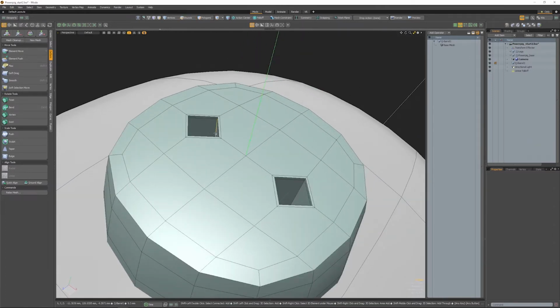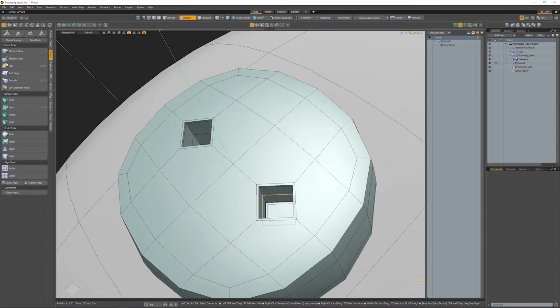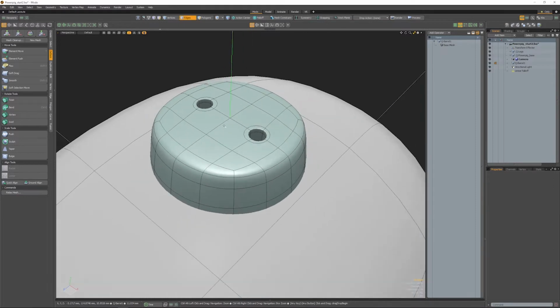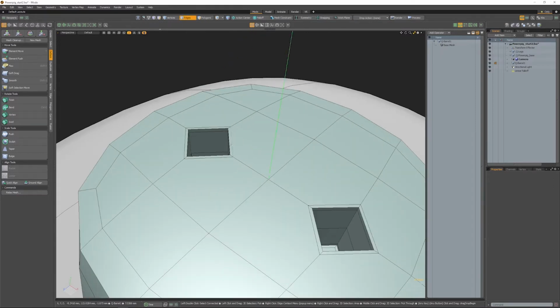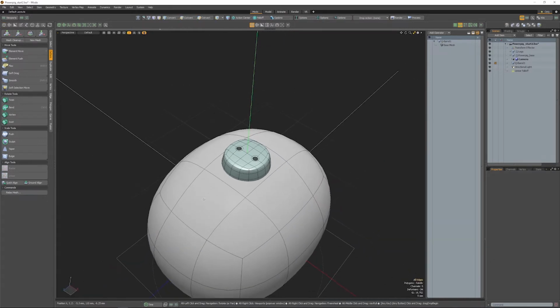It's a little bit too sharp for my taste, so I wanted to have a little bit smoother radius. So I'll just add another loop here, and so I need to pull these edges a little bit back to have a smoother radius. So double click, R to scale, scale a little bit out. Same on this one. And now on the vertical ones, just W to move, and move this one also, and that's it. Subdivide with Tab, and alright, so I'm happy with this one.